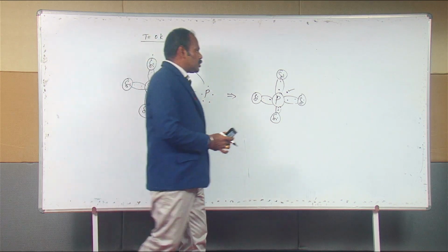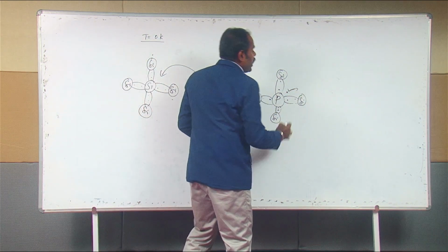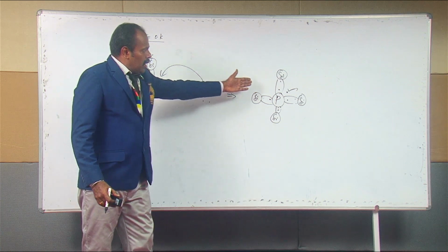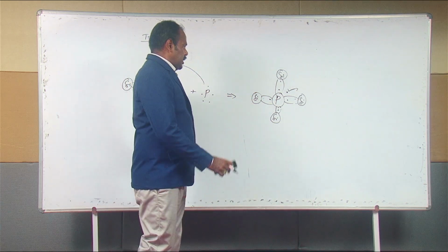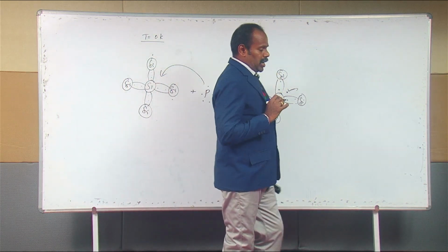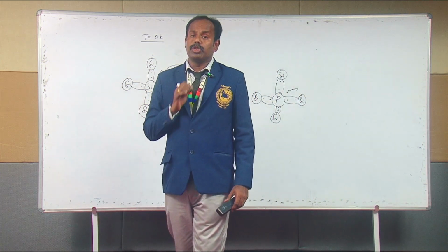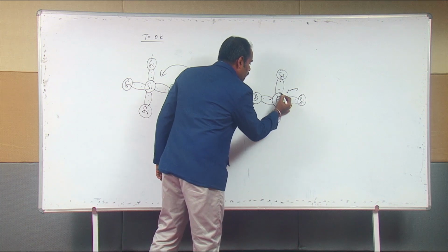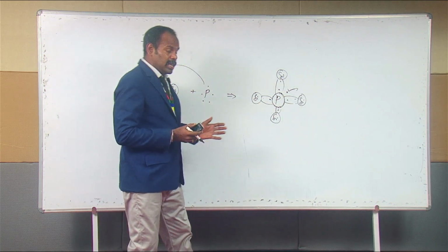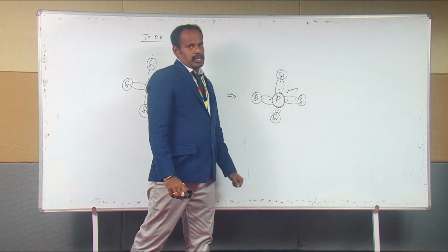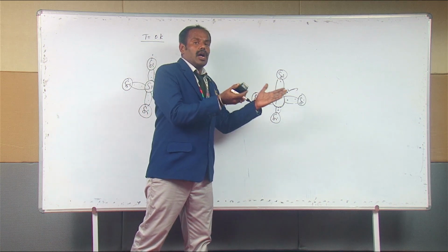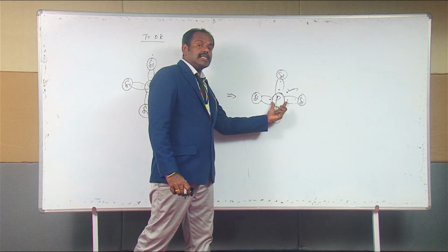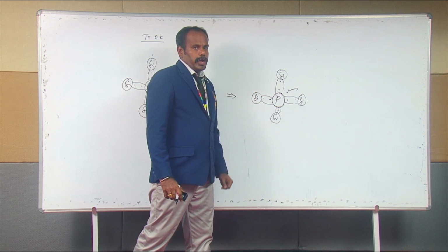So, what concentration is being increased now? The concentration of free electrons is getting drastically increased by the addition of the impurity atoms. Right? Fine. Now, as I mentioned, this impurity atom is called a donor impurity atom. What's the reason? Because this phosphorus impurity atom, after being added into the intrinsic semiconductor, is donating a free electron into the system, or giving a free electron into the system, and that's the reason why the impurity atom is called the donor impurity atom.